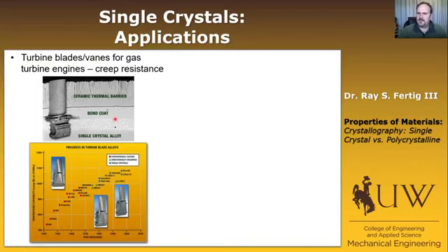But basically, this is showing you the turbine vane, or turbine blade, right here, and this is the surface. So you're looking at the structure here. This is kind of a zoom in of what the actual surface is. You have a single crystal alloy, then there's some sort of a bond coat, and then you have a ceramic thermal barrier. Okay, the reason that the single crystal alloy works is because, as gas turbine engines run very hot, it prevents the long-term creep growth along that blade.